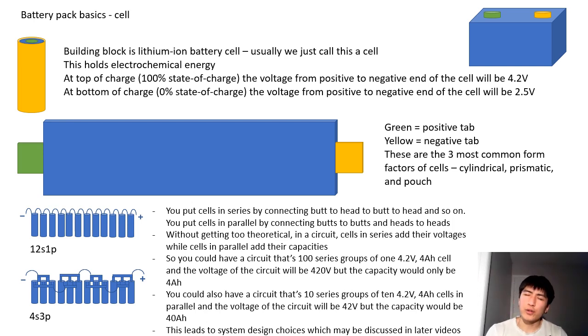And if you go under voltage too many times, the current collectors, which are on the edges of the cell past the cathode and anode, will have their copper ionize and turn into ions, and then the copper will form dendrites that will short the cell. So you don't really want to stray outside of these normal limits, which are considered the normal safety limits.